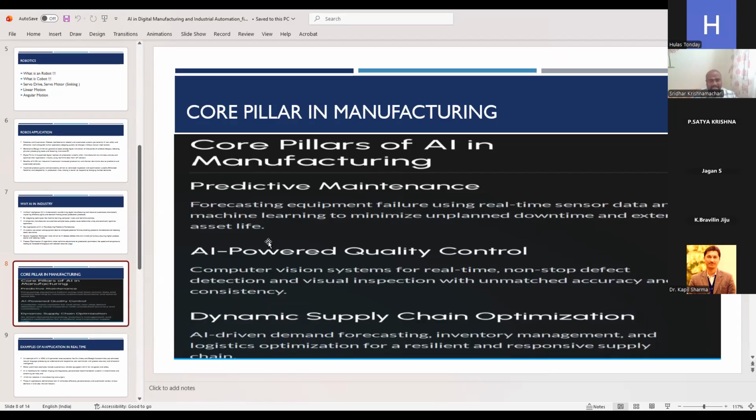So the main intention is data capturing. For example, the machine is running continuously for 360 days. We have to compile it by bifurcating it into 12 months, right? In those 12 months, we need to do predictive or preventive maintenance based on the machine running hours. If the machine is not running, then based on the running hours only we have to do this maintenance.